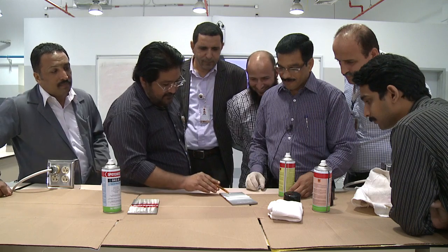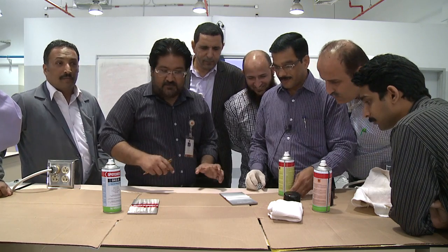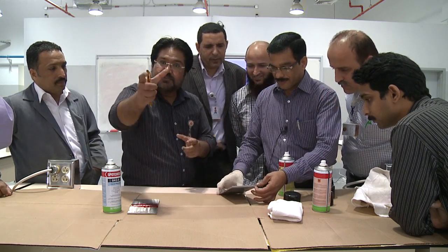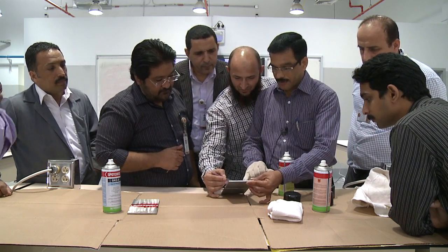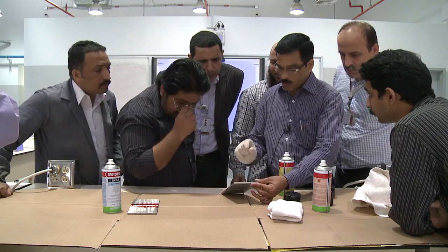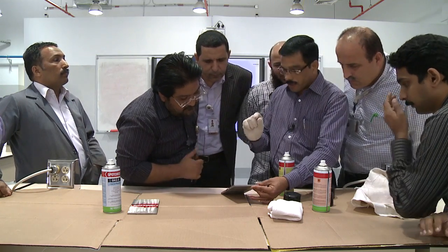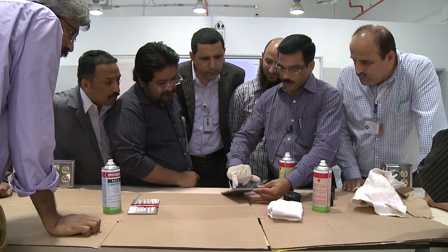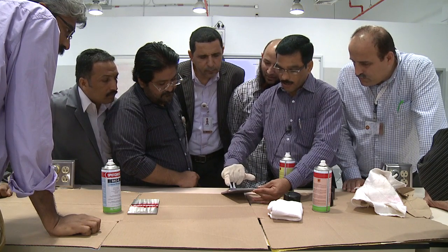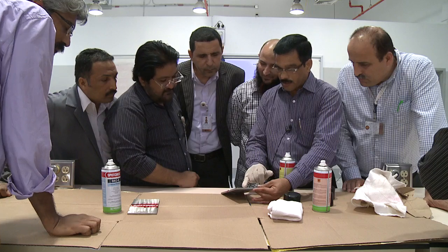So we can clean this one back and clean the other one at one time. Now see, here it is also coming. Yeah, because this crack is a very tight crack. That's why the indication is coming as a very narrow line. So one line is a very tight crack and one vertical crack is here.